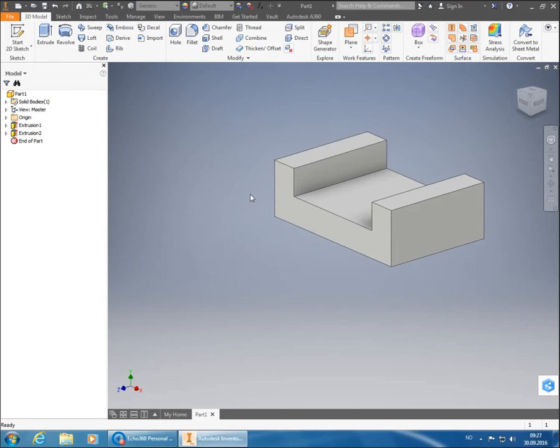When we're in this sketch, we want the rectangles to be on it, right? Look at this part. So when we do the rectangle, we want to put the side here, down to here, not down here, on it. Then you see it snaps and it says 60. So we only want to do this, 50. Then you have it. So do the other side. It doesn't matter which corner, just one. Click it. Yeah, pull down.